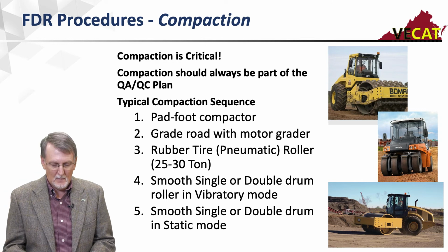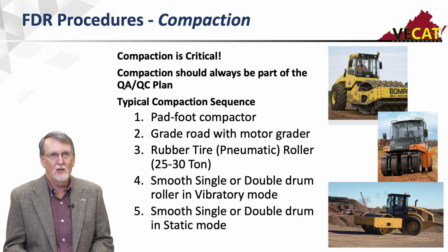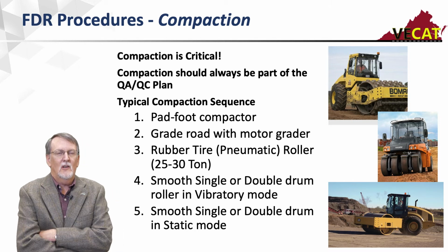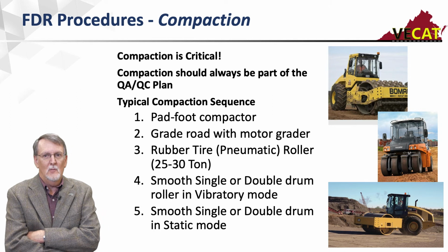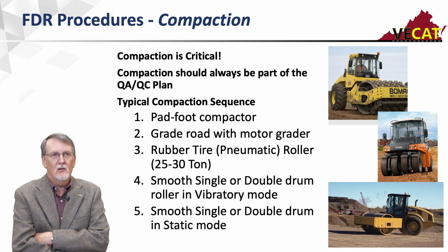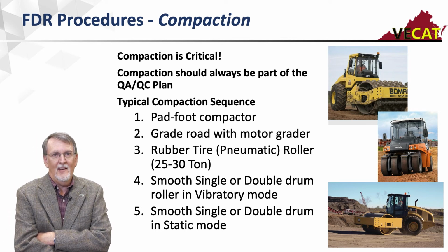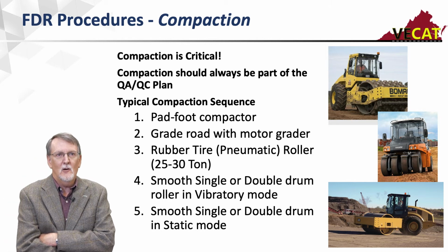Compaction. Compaction is critical, especially with mechanical, pulverization, and bituminous. It's not quite as critical with cementitious because I'm going to cement stuff together, but I still want everything adequately compacted. And because of the thicker depths, I typically am going to use a pad foot compactor, which will allow me to compact this material from the bottom layer up.